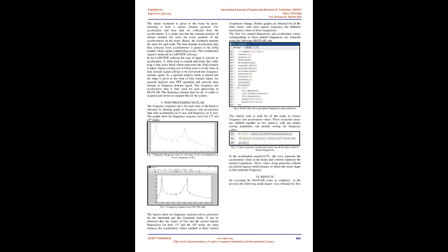Experimental setup consists of an FFT analyzer with computer and its accessories. For further analysis of the effect of different end masses on the natural frequency of the cantilever beam, the free end of the cantilever is loaded with different masses along with the accelerometer, and the result of this experiment is observed on the computer screen for the aluminium and iron beams. Then the author has concluded that numerical and experimental results are comparable.